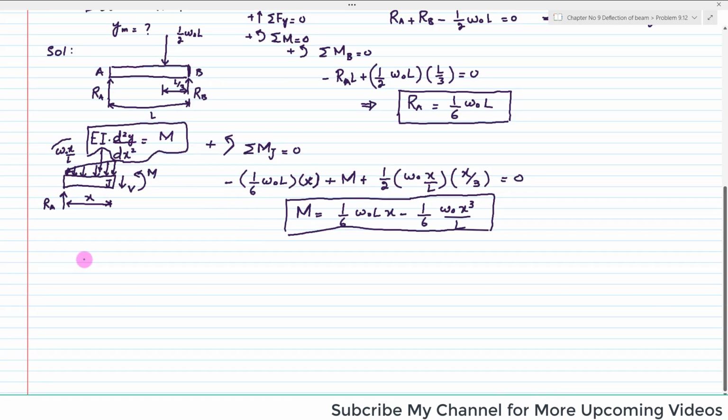Clear? So we will get EI into d square y over dx square is equal to 1 over 6 W naught Lx minus 1 over 6 W naught x cube over L. Clear? Now let this be equation number 1.